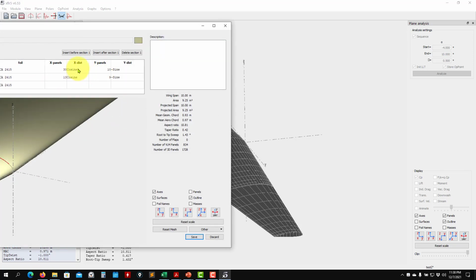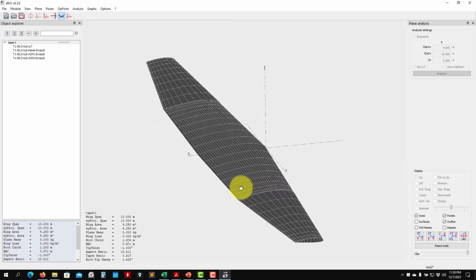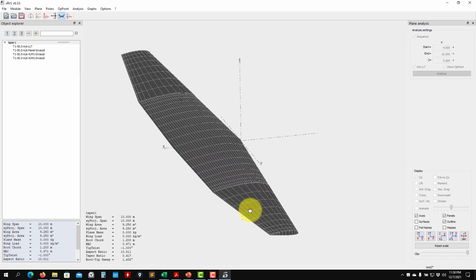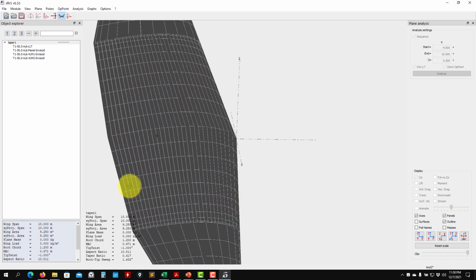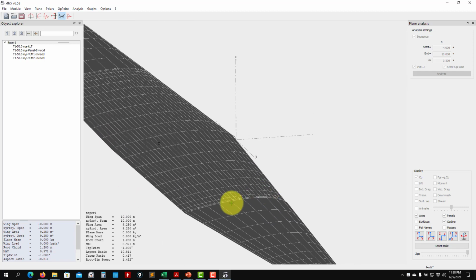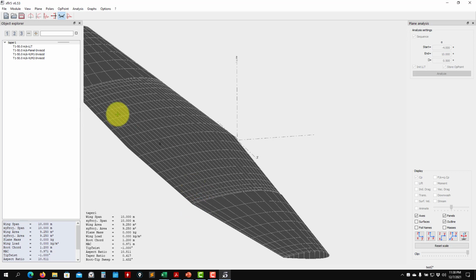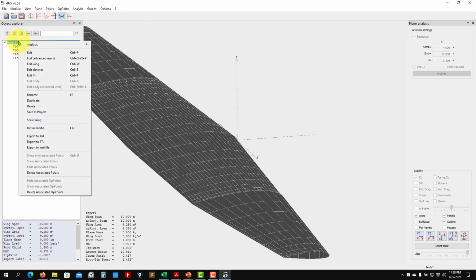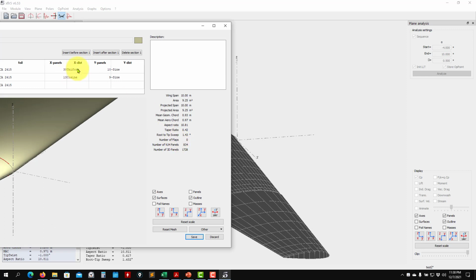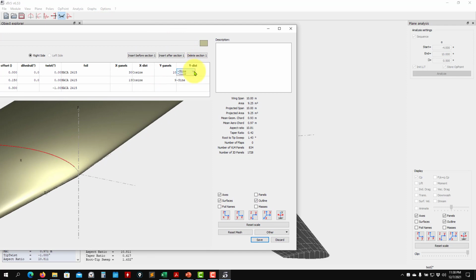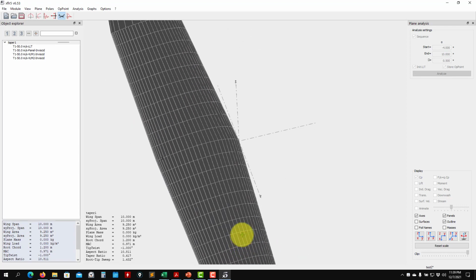And this option represents the distribution. I want a uniform distribution there. You have it there. So it is recommended to have more panels towards the leading edge and trailing edge. So that one you can leave enabled. But in this case, I don't need it. So this might be a source of error. I want it uniform. So you go back. This one you can leave. And we want this one uniform and uniform. And see that you have this. Okay, much better.